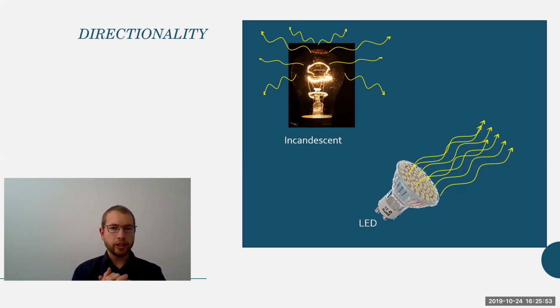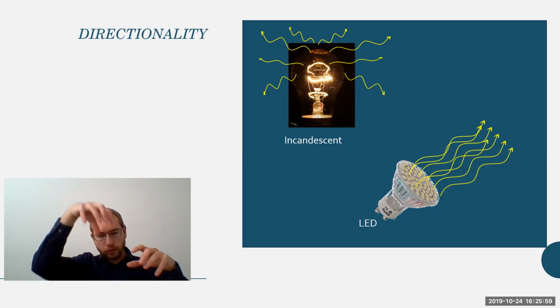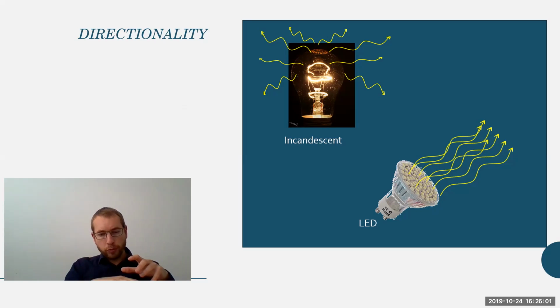It was a fire station that our office was recently auditing. They had replaced them with LEDs. And because the light was so directional now with the LEDs, it was pretty much black underneath the fire engines, and people had a really hard time. They had to wear headlamps working up underneath the cars. They didn't used to, because they used to have halide lights which sent wavelengths off in every direction.